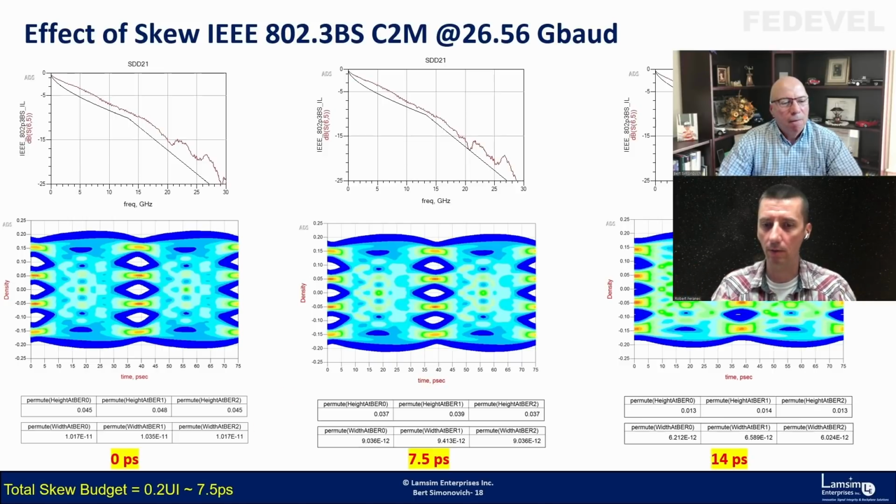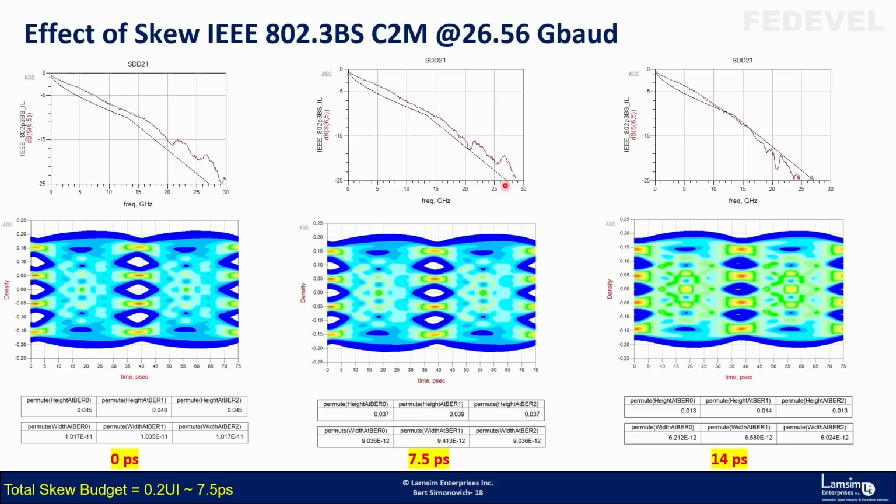So basically this graph includes also the skew. Yes. The skew is causing this loss, more loss. Because what's happening is the skew is causing that resonance. You can't see it in this dip, but here there's no skew. So that big dip is way out in frequency, right? But as you're having skew, you're going to get that dip getting closer and closer.